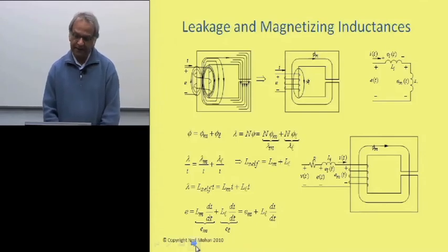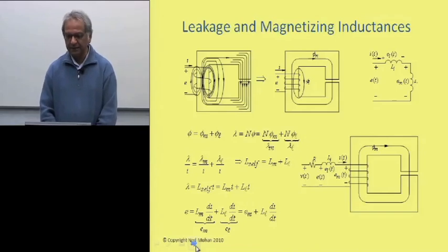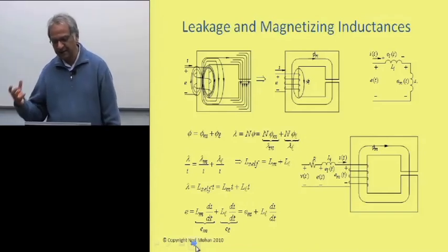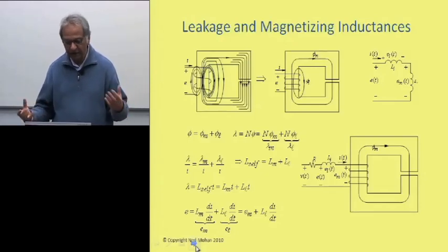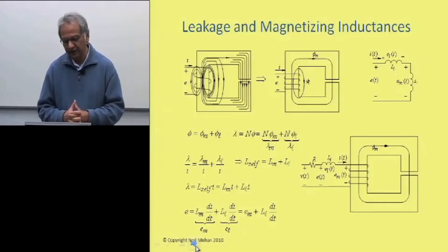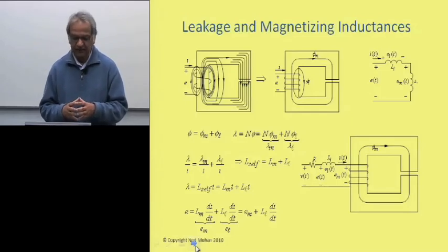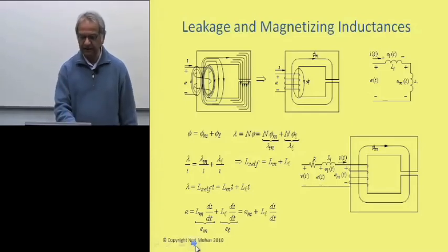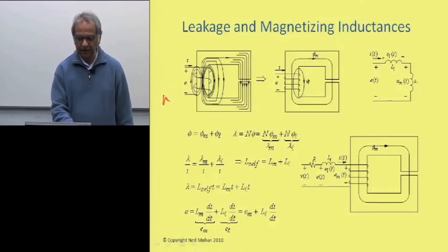But in magnetic circuits, because the relative permeability between the air or free space and the magnetic material is not too different, unlike copper and air for electrical currents, we will have leakage. So let's say in this magnetic structure, you have this coil of N turns, and our intent is to produce flux through the air gap over here.